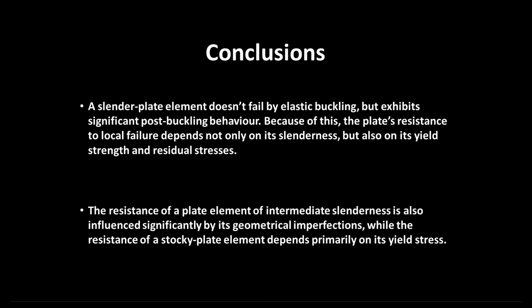From the conclusions, what we learned: a slender plate element doesn't fail by elastic buckling, but exhibits significant post-buckling behavior. Because of this, the plate's resistance to local failure depends not only on its slenderness, but also on its yield strength and residual stresses. The resistance of a plate element of intermediate slenderness is also influenced significantly by its geometrical imperfections, while the resistance of a stocky plate element depends primarily on its yield stress.